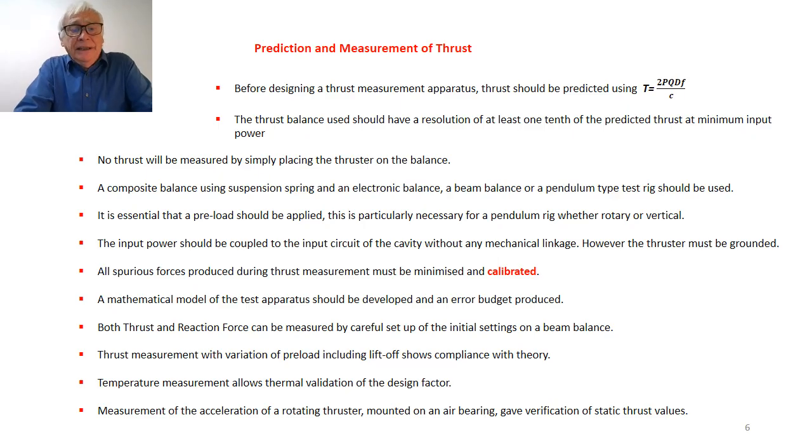And finally, if you do measure the acceleration of a moving thruster, either rotating or in a vertical thrust measurement arrangement, you can verify the static thrust that you will have measured by simple application of Newton's laws, which is a very satisfying thing to do.